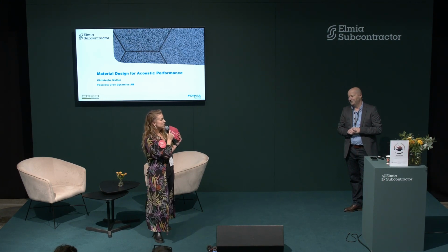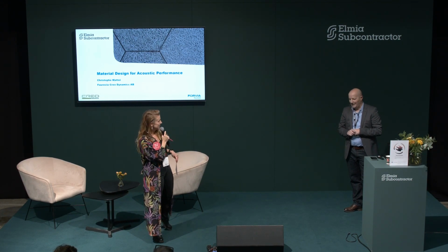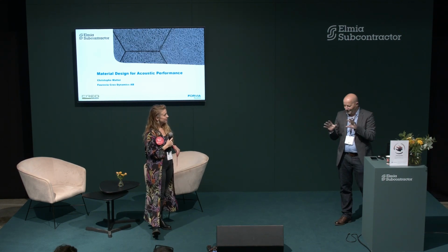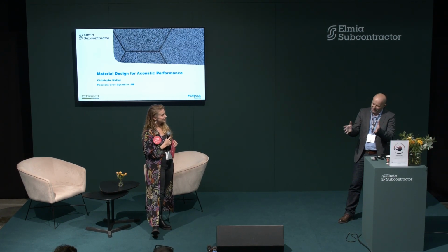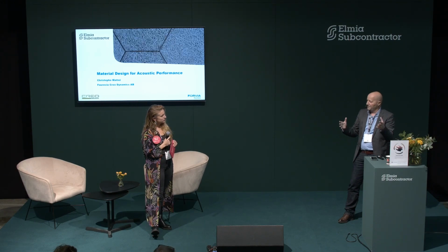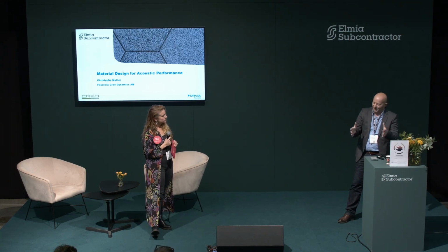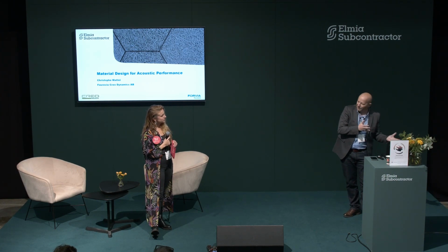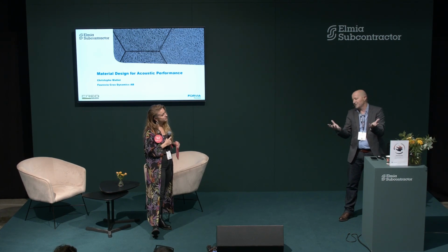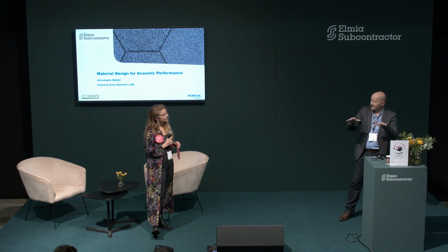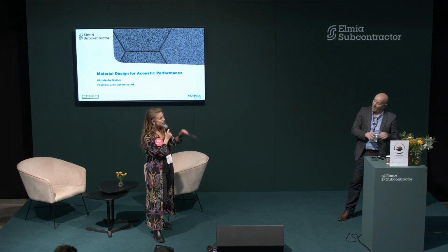And why do we need two different techniques? They are working in different ways. I will show typical performance of materials. Usually, passive materials are working well in middle and high frequency. It's tougher, or you need a lot of material, to attenuate sound at low frequency. Active noise control, on the other hand, is very efficient at low frequency. It's more challenging at high frequency, though. So you can say that it's two techniques working in a complementary fashion, for low and high frequency.